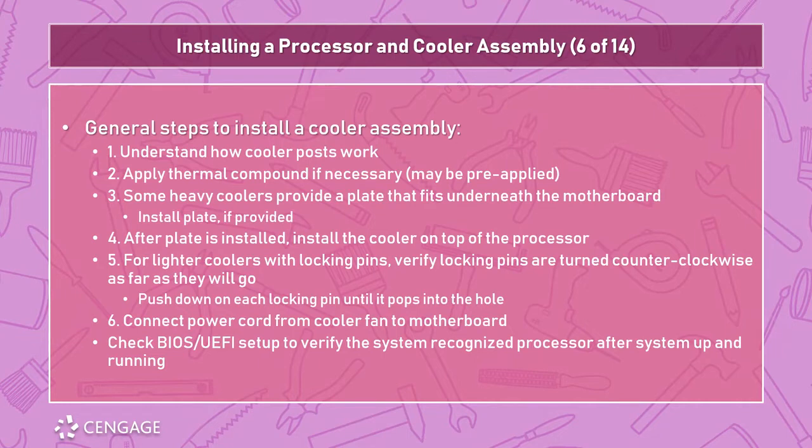Once the cooler is mounted, just give it a little wiggle and see if it has any play. If it does, figure out why and eliminate it. It may be that one of your locking pins wasn't turned all the way, or one of the screws, if you're using a Wraith cooler, wasn't tightly screwed down.